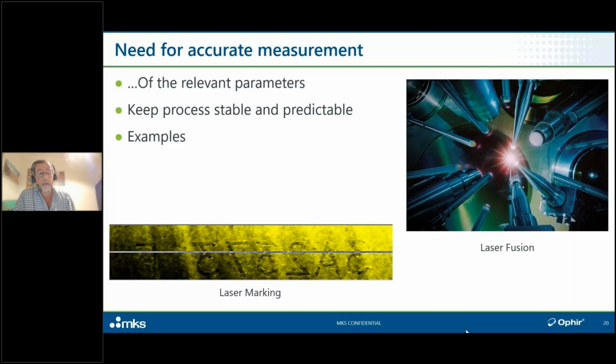And they want to locate every jet engine on the planet that has in it a blade that was produced on that same machine on the same day during the same shift, so that they can do preemptive maintenance. Interestingly, the laser marking system used a laser that was something like 18 or 20 watts. It's not a lot of power, but when it's focused down to a small enough spot, it can burn a serial number onto the metal of the blade.